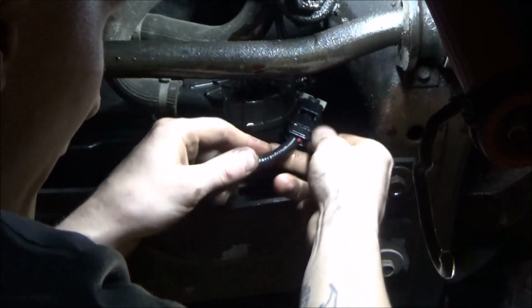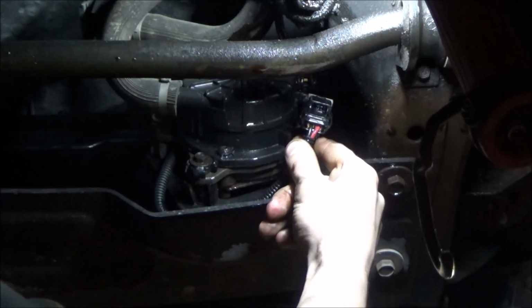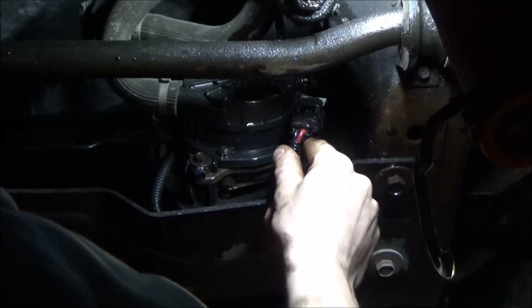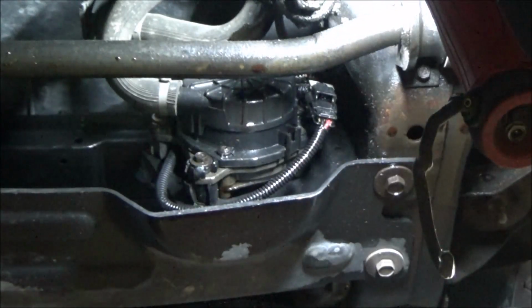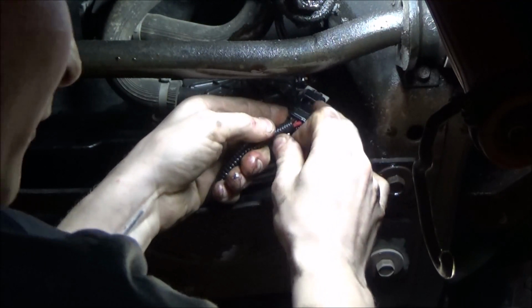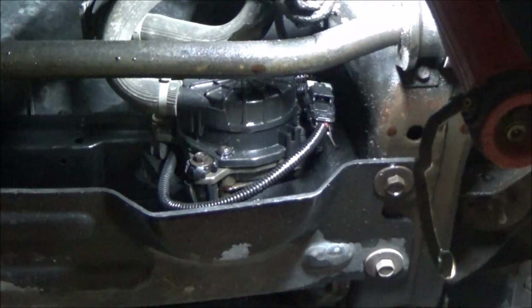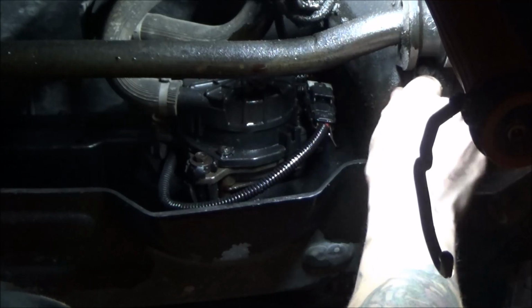So now we can hopefully see this connector a little bit better. We can manipulate it. As we can see, we have a black wire, we have a red wire. We're going to start, guys, with a test on this red wire first. I'm fairly certain that this is going to be the power feed from the relay to turn this motor on. We're going to do that in much the same way we did this solenoid here, guys. I'm just going to slip this T-pin into the back side of this connector very gently so as not to cross-thread it. I'm then going to reconnect my test light to a ground location. I'm going to use the same one that I used for the solenoid because we had good success with it.